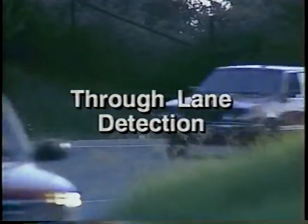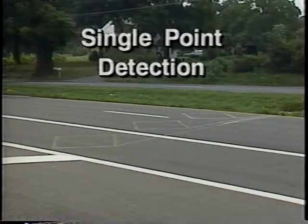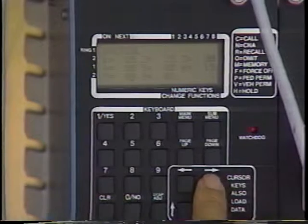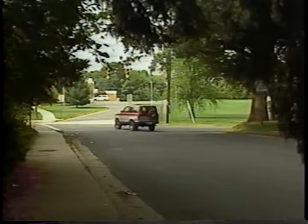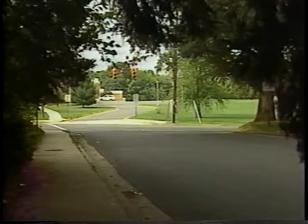The detection of vehicles in through lanes depends on the approach speed and the controller operation type. Detector designs for through lane detection include single point detection, loop occupancy detection, and high speed point detection. Single-point detection is the simplest form of through-lane detection used for actuated controllers. Located 2 to 4 seconds of travel time in advance of the stop line, a point detector requires very specific controller timing. Appropriate primarily for low-speed approaches, this type of detection is popular for the side streets at those intersections using a more complex detector on the major arteries.